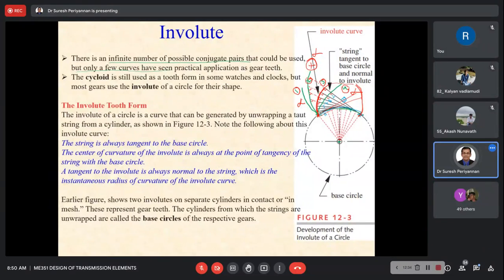Now this is one tooth. Now this is the teeth design, such that we are defining our tooth profile. So now this is a very important terminology: involute. The involute curve is mostly used in spur gears and helical gears. This is the kind of tooth profile we are following.